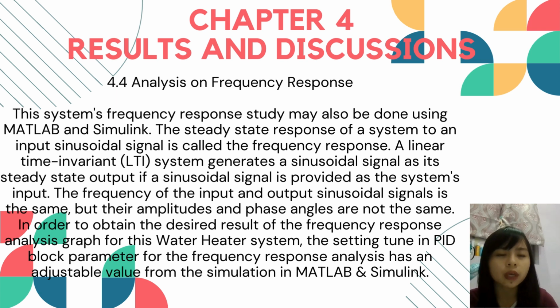The frequency of the input and output sinusoidal signals is the same, but their amplitudes and phase angles are not the same. In order to obtain the desired result of the frequency response analysis graph for this water heater system, the settings tuned in the PID block parameter for the frequency response analysis have an adjustable value from the simulation in MATLAB and Simulink.